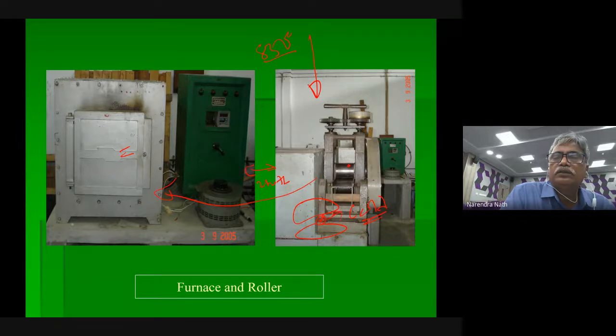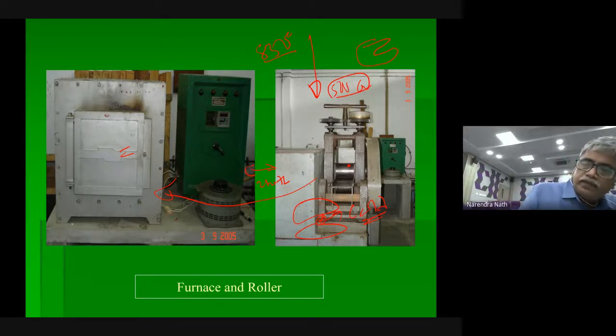It is coming down to 500 or 600 in that range. So further, if you place it once again, the button will crack like this. That's why you put it back again, raise the temperature up, and wait for a while. When it reaches 850, then you take it and do it like this. This way we did hot rolling.